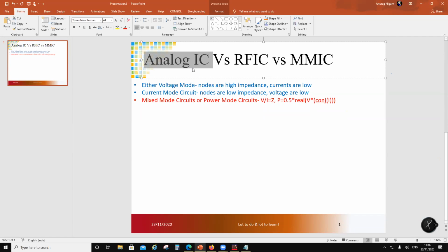As soon as you put differential circuits, the noise is solved because the common mode noise basically goes away, since common mode gain is very small. If you make differential circuits, there's another advantage. The common mode input voltage range is large. What it means is that even if your bias points drift, you are in a very large common mode input voltage range, so nothing happens to you.